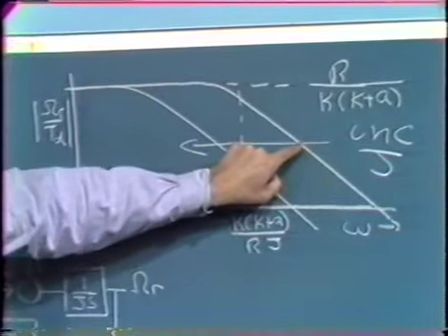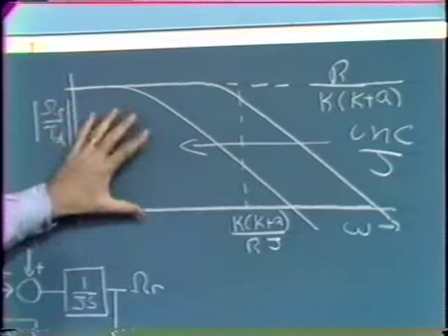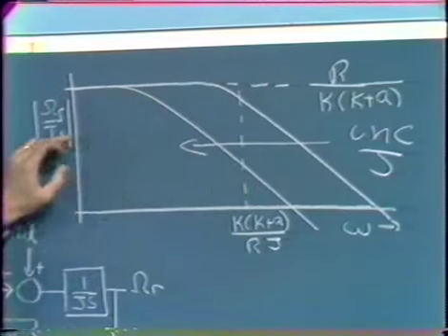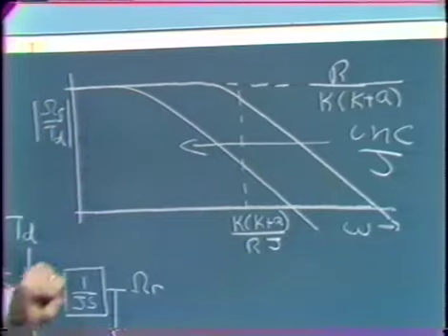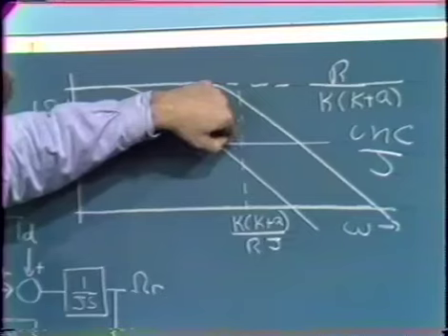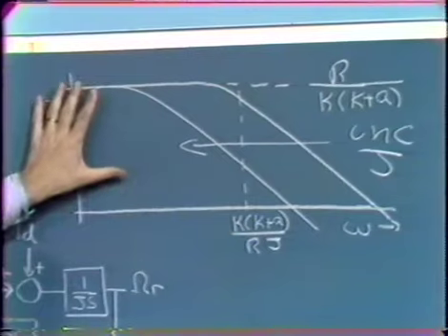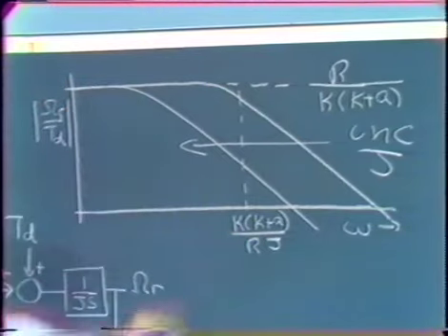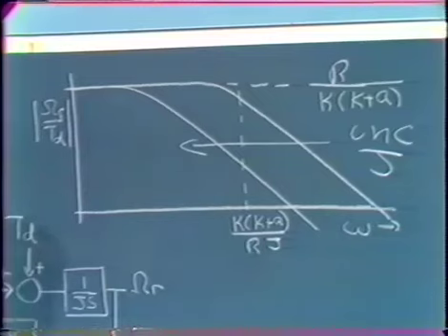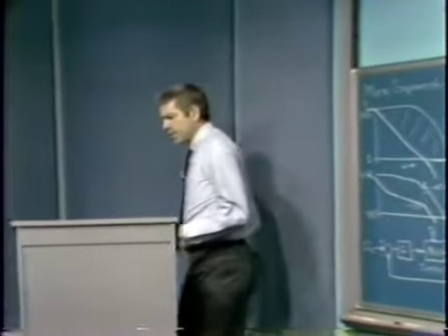And we see that the rejection of the system, remember we'd ideally like to have this transfer function 0. We'd ideally like to have no change in speed for a given torque disturbance. But we push the first pole down as we increase J, and in fact in the limit we could increase the band of frequencies over which we got very high attenuation by using a sufficiently large rotating inertia. So in this one important class of systems, regulators where the objective is to reduce or ideally eliminate a disturbance, creating a dominant pole is probably the compensation form of choice.